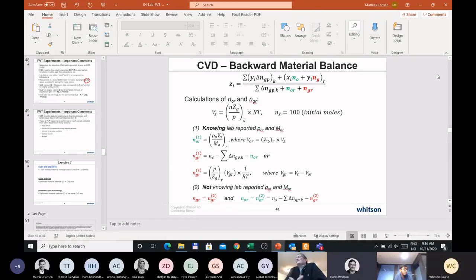Yeah, I mean, if you ask me, I would say it's not very important getting the temperature right. You're not going to be very far off. And then once you tune your equation of state to, let's say, 3 CVDs from 3 gas condensates through the column, and you find out that all 3 temperatures are somewhat off, you decide later, well, it doesn't really matter because you're tuning the equation of state to the 3 sets of data at almost the right temperature.